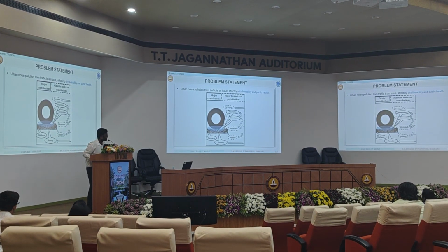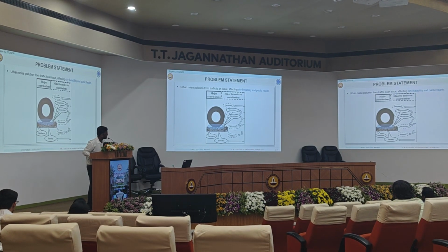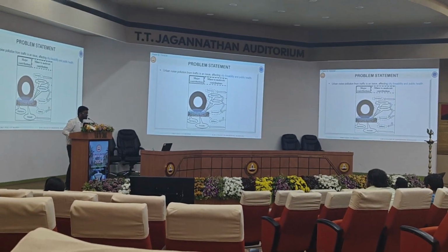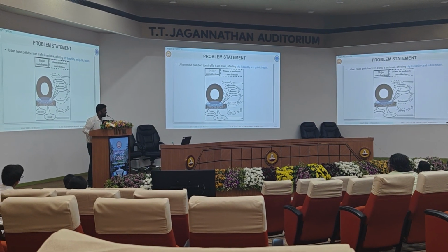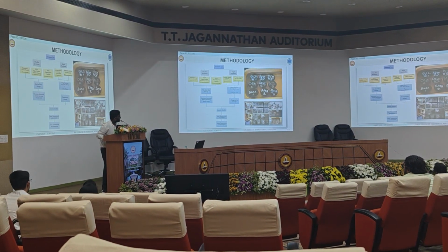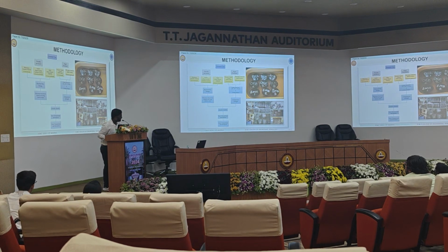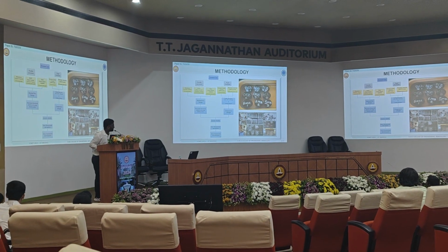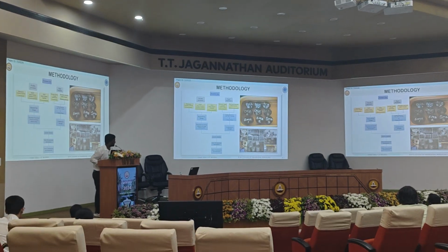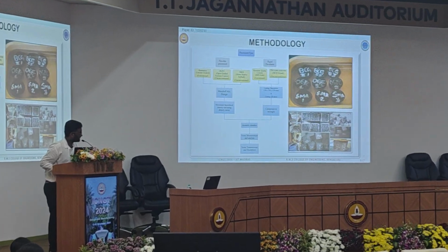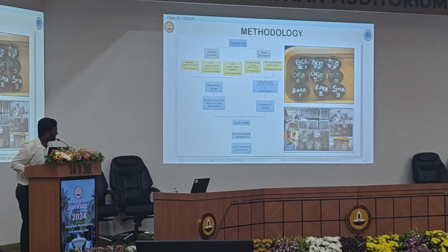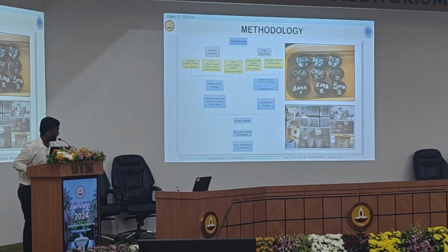And there are a lot of factors like pavement unevenness, megastructure, macrostructure, microstructure, stiffness and porosity, as well as the thickness of the pavement that affect the noise generated by traffic. This particular study mainly deals with the tire-pavement interaction generated noise. As per this methodology, the flexible pavement was compared with conventional as well as unconventional pavements, and the rigid pavement was compared with the conventional and unconventional as well. In case of flexible, conventional was bituminous concrete grade 2, which was compared with the unconventional OGFC, which is open graded friction course, and the second unconventional one, stone matrix asphalt.